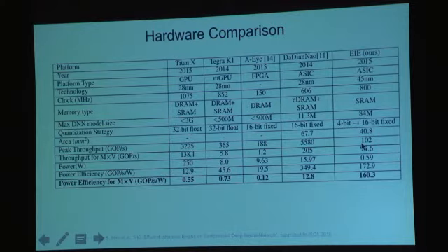And if you look at how it does on the whole operation, the real winner here is DaDianNao, because for the convolutional stages, it can sustain very high GOPS per second. But if you have to implement some fully connected layers with a batch size of one that don't fit on chip, you quickly wind up with poor efficiency for matrix times vector, and we do a lot better with the efficient inference engine. Even so, that winds up in GOPS per watt doing quite a bit better than you'll do on the GPUs. So there is advantage to fixed function as long as you're not limited by memory.